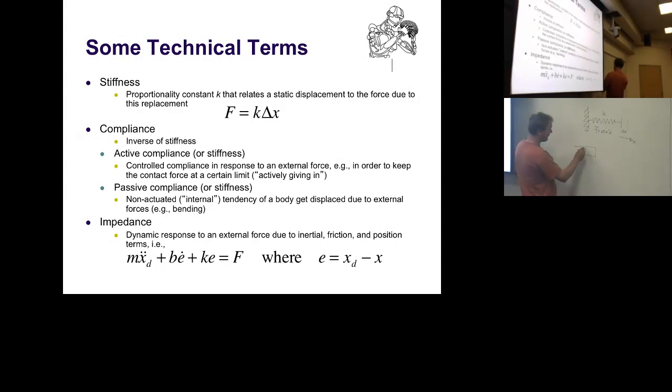There is something like a piston, and it has hydraulic fluid in it. There's something attached to this thing, like this, and then this creates a force, F, and you pump fluid in here, or you pump fluid in there, and then the piston moves back and forth. Very straightforward. But oil turns out to be an incompressible medium, to the best of our physical interest, let's put it this way. That means if you push this thing back and forth, it's great. But there's no compliance at all. If you push against it, it's nothing.